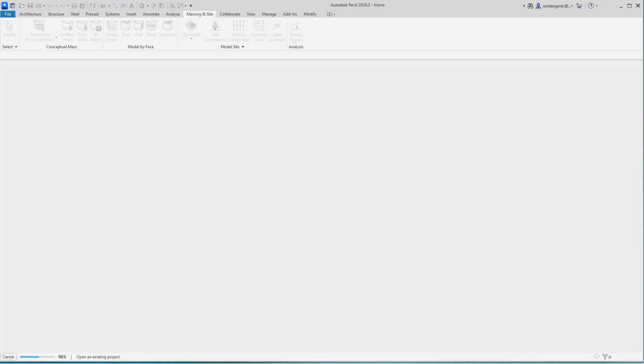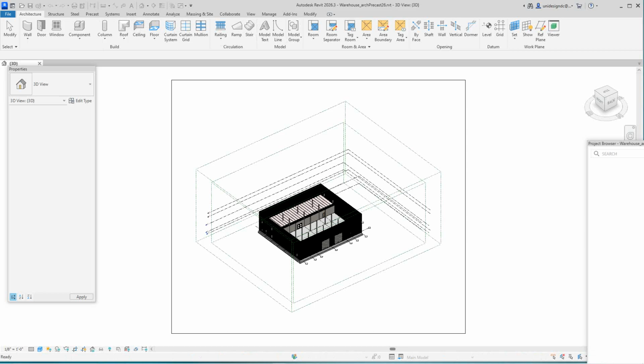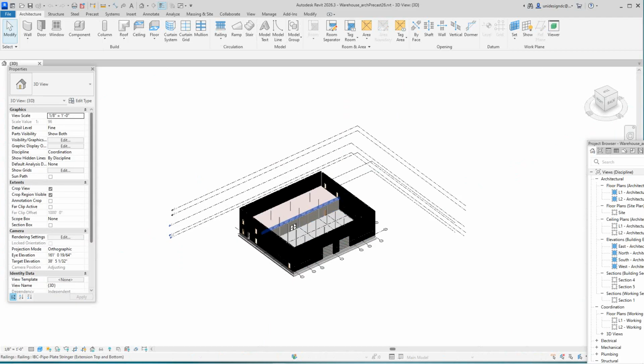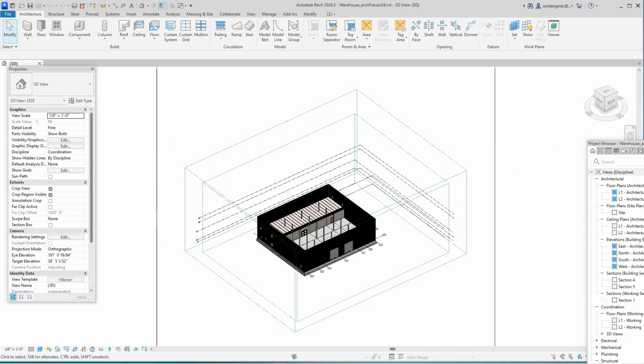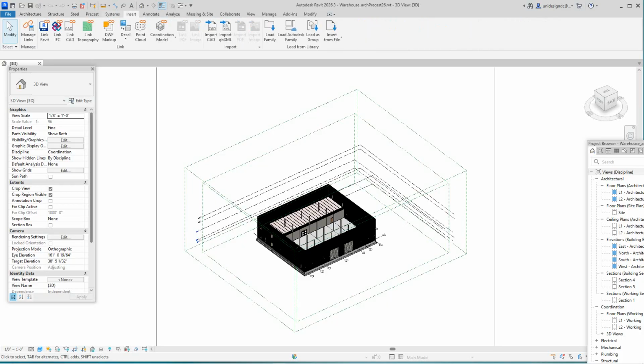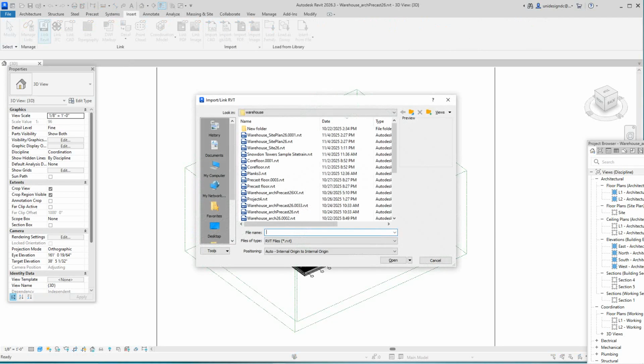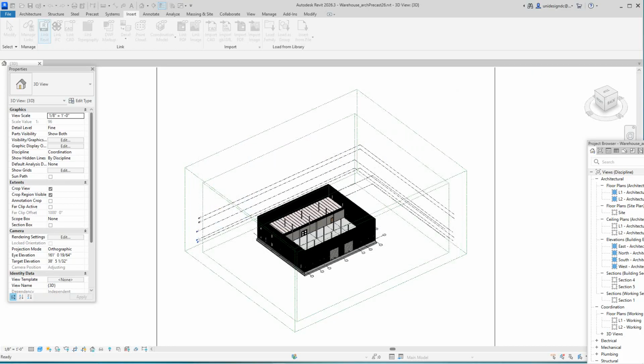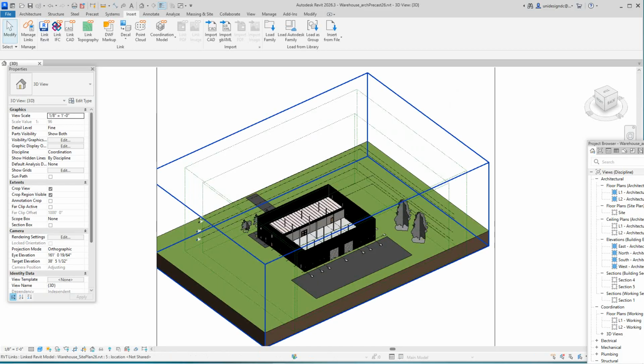And then what's beautiful here is we can show different linked files. So far we're going to have 3 files linked into this architecture file. We've got our plank, we've got our AutoCAD drawing. And so now what we're going to do, I'm going to insert a Revit link here. And I'm going to find our site here. Origin to origin, okay. And there we go.